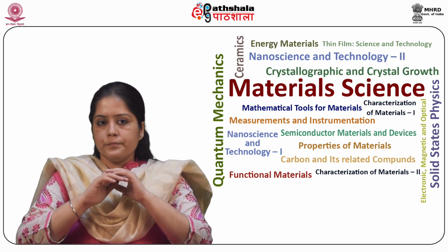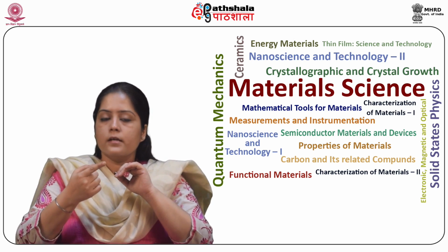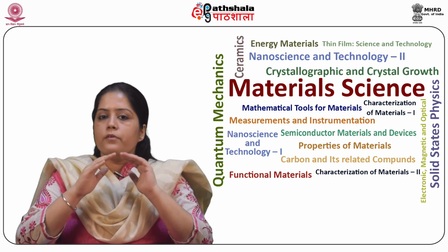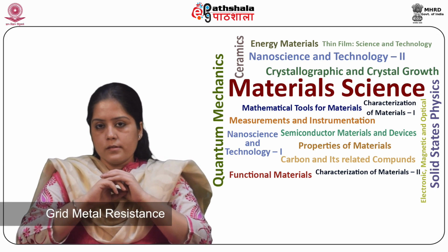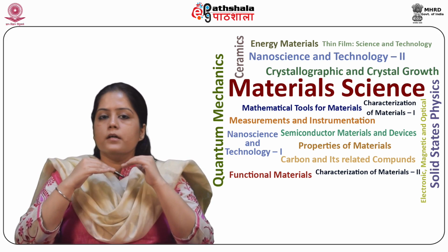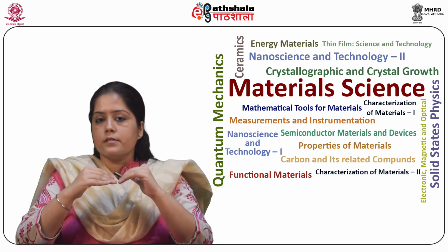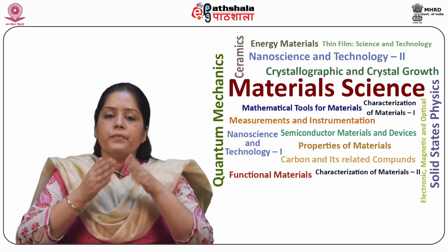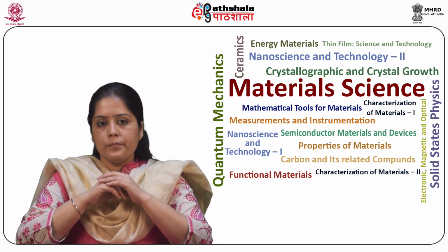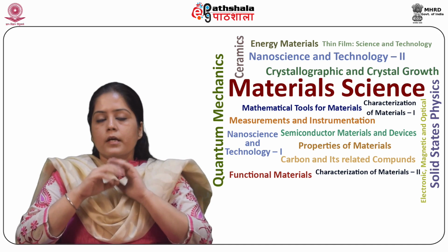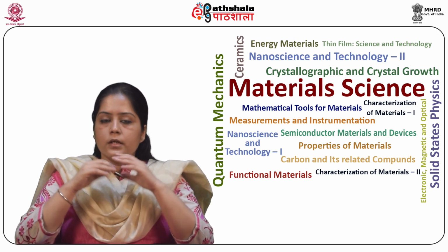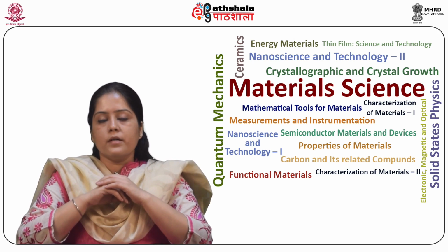First, it increases the series resistance in the form of grid metal resistance. Second, it gives a surface contact resistance between the metal grid and semiconductor material. And third, it reduces the light transmission reaching the semiconductor.